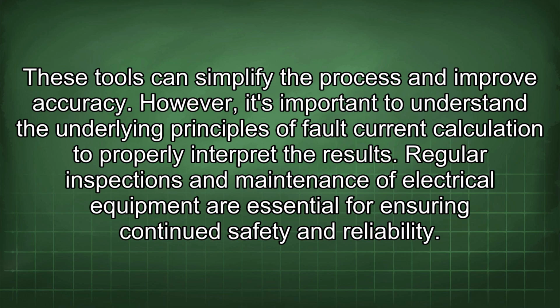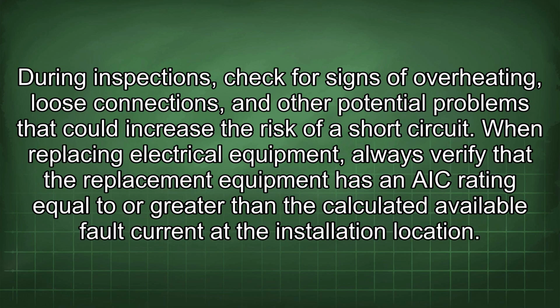Regular inspections and maintenance of electrical equipment are essential for ensuring continued safety and reliability. During inspections, check for signs of overheating, loose connections, and other potential problems that could increase the risk of a short circuit. When replacing electrical equipment, always verify that the replacement equipment has an AIC rating equal to or greater than the calculated available fault current at the installation location.